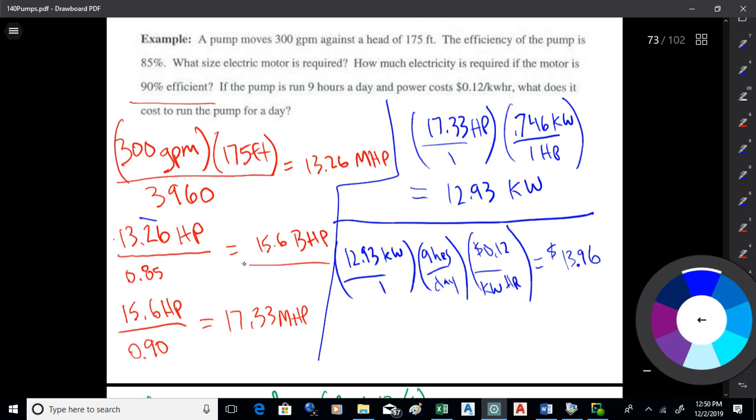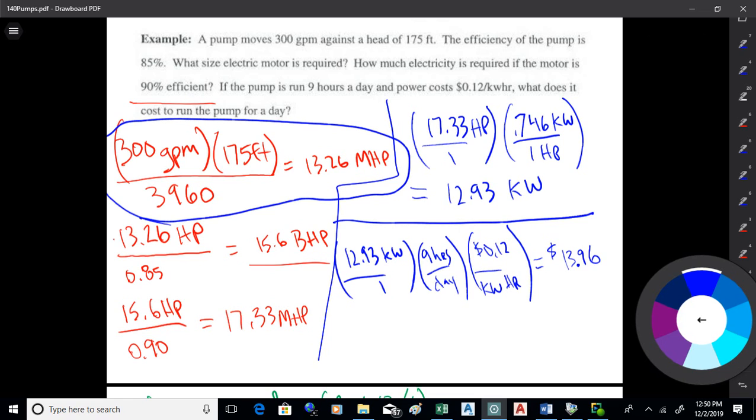So that's how you back out. We started here, here's what I have to do. But if we know these efficiencies and we know the cost of power, we can figure out what it's going to cost, okay? Y'all all right with that? Just depending on the direction we're going, we multiply or divide. Think about whether you want the number to get bigger or smaller. If it's going to get bigger, which normally it is, we walk it back, divide the efficiency out, and that will make it bigger. That makes sense. So that's the basic numbers that you run if you're going to analyze your pump system.